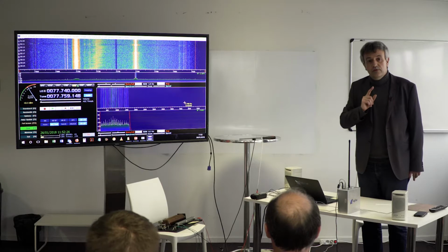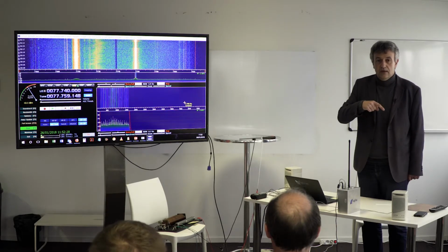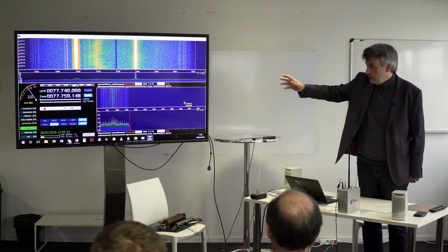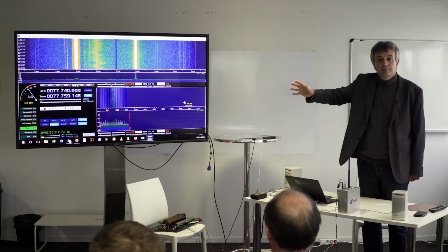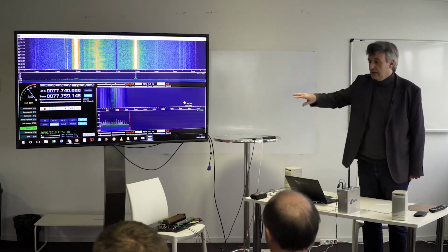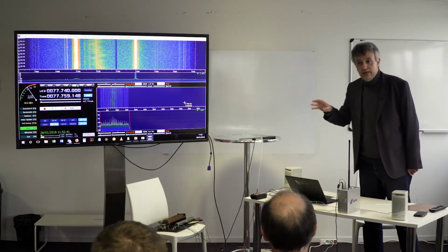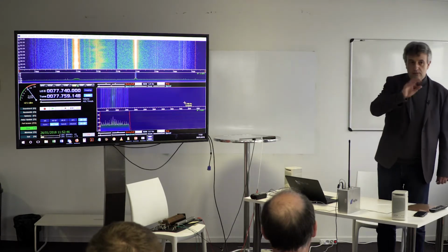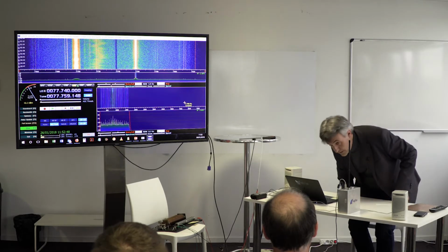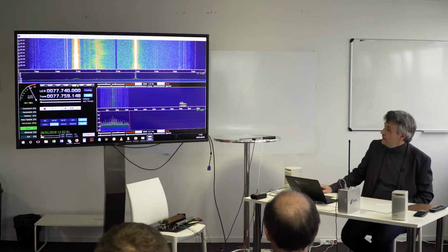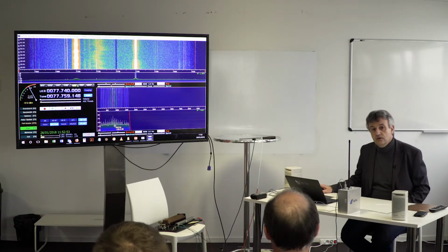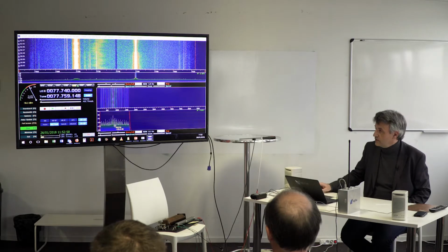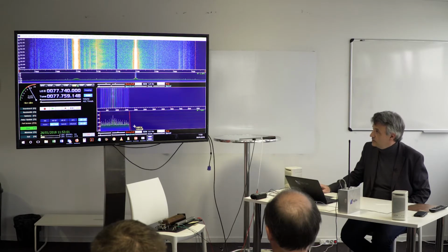You've seen the difference without the tuning device, and with the tuning device. It's a huge difference. We've gained, I don't know, probably 20 dB. Maybe more. At least we've won a bunch of dB, okay? Now it's okay, you can stop. Now, can we have FM service? By the way, all those spurious are the 50 hertz spurious, so we probably have a power line somewhere which is disturbing the transmitter. But anyway, it's not a big issue.